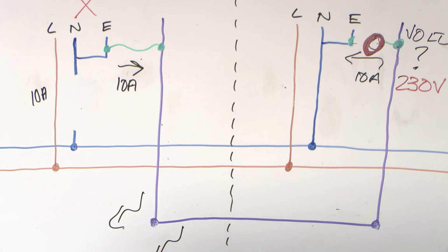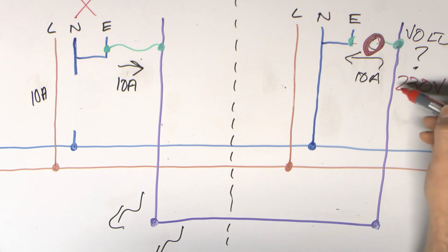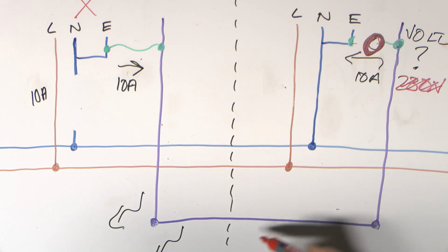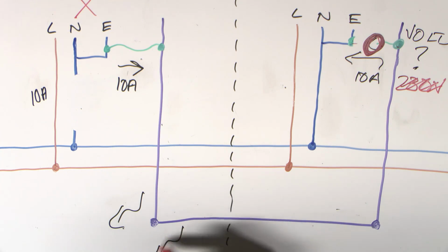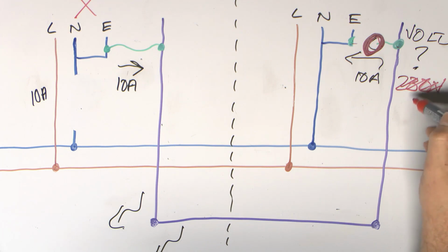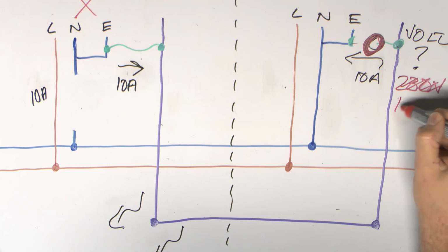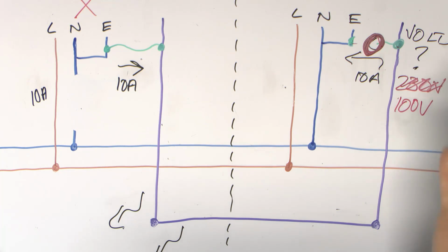this scenario. If this is buried in the actual ground outside, this is going to be somewhat less, because some of that current is going to be going away into the ground here. Needless to say, it's not going to be 0, so you might find, say, there was 100 volts there or something. All depends on the exact circumstances, and of course you won't know these circumstances because you can't see next door's gone off and you can't see the property up the street has got a problem and all the rest